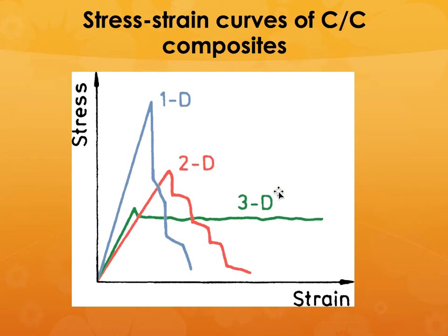And you can also have a separate toe material that is going in the thickness direction. So if you have fibers only in one dimension, it will have the properties that are related to these fibers in the 0-degree orientation. So you are going to have pretty strong material, but then it starts weakening and starts breaking down. But if you had fibers in both the 0 and 90 direction, then it will start showing much better composite behavior. And if we had fibers in the 3rd dimension, then you can have a 3D fabric.